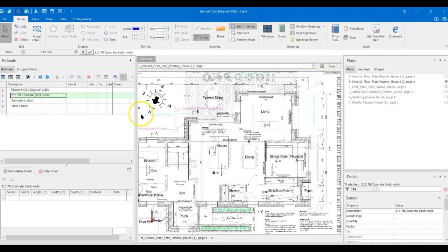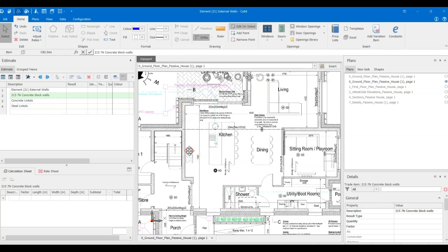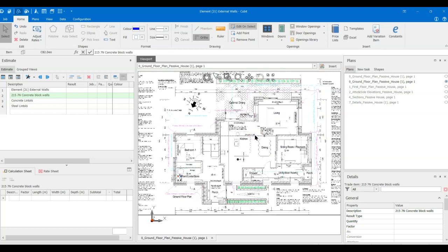A query that came up the last day in class was in terms of vertical area. Up until now, I've been teaching this in vertical area. Vertical area is probably the most correct way to measure these drawings, but a question arose, could you actually just measure from the elevations? Yeah, if the elevations are measured to scale and you're satisfied with that and you can read the drawings correctly, there's no reason why not. Most people will read the plans a little bit easier than they'll read an elevation. All of these little extension pieces, for example, are difficult enough to pick up off the elevation, so the depth in plane is more difficult to read. If you can read them well, if you're used to it and you're in a hurry, then by all means use the elevations. But for more accurate measure, I would suggest you use the plans, which is what we're going to do now.